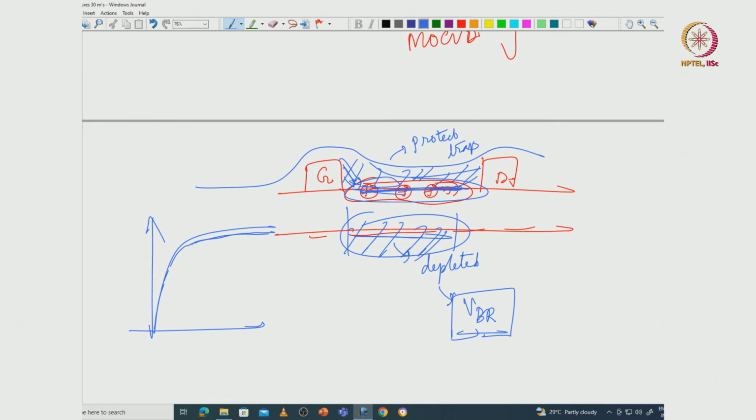and this depletion region will be compromised, because this depletion is sustained by this surface traps getting neutralized and again not neutralized. So, if you are preventing that surface traps from getting neutralized and not neutralized, then you are essentially preventing this depletion region also from forming as much, and so your breakdown is to some extent compromised. So, an exceptionally good passivation scheme will lead to a lower breakdown, okay, and so that is a compromise you have to make. So, you want some amount of collapse, maybe 10% collapse, but you want the breakdown to be not so compromised, so that you can still bias your device at 28 volt or 50 volt as the case may be. So, this is the concept of the passivation and the virtual gate.